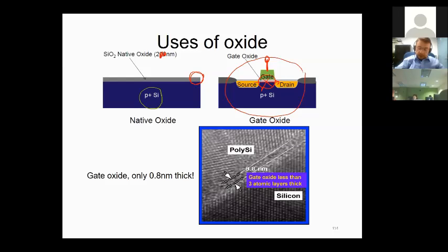And the importance is, here is another electron microscope image. So you can see the thickness of the gate oxide here. It's only 0.8 nanometer thick, or 8 angstrom thick. So we have the gate as the polycrystalline silicon in this case. So I can see some arrangements of the atoms, but it's not going to be like the crystalline silicon, where I will end up with what we call the grain boundaries. As for the silicon, I have a fully nice arrangement here underneath. And here I again end up with the amorphous material that I was emphasizing.